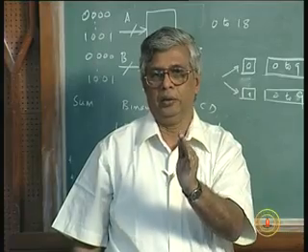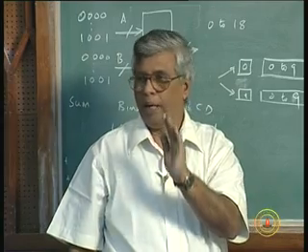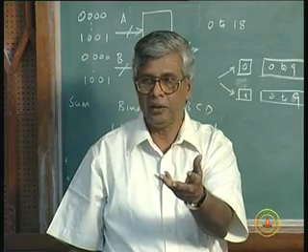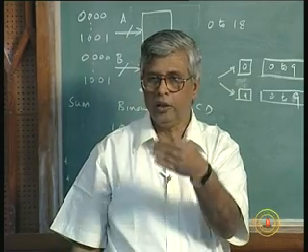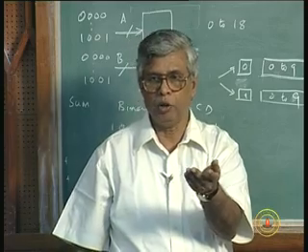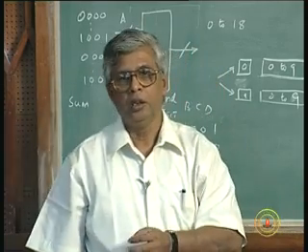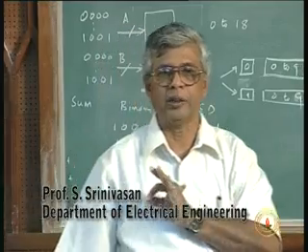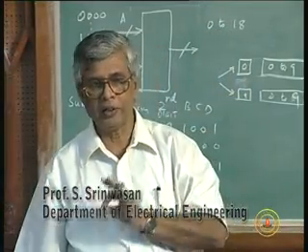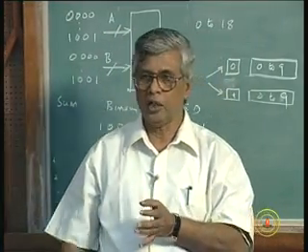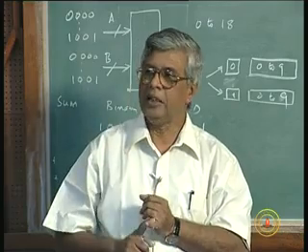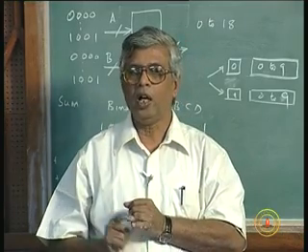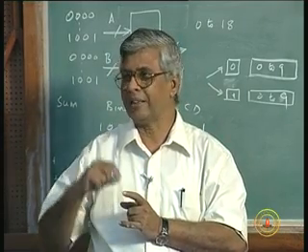6 has to be added, no problem. I have to take the binary addition, I need to take another binary adder, a 4 bit adder, and add 6, but it is not that simple. I can only add 6 under certain circumstances. What are the circumstances under which I have to add this 6? It depends on whether there is a carry in the original addition, or whenever the number exceeds 10.